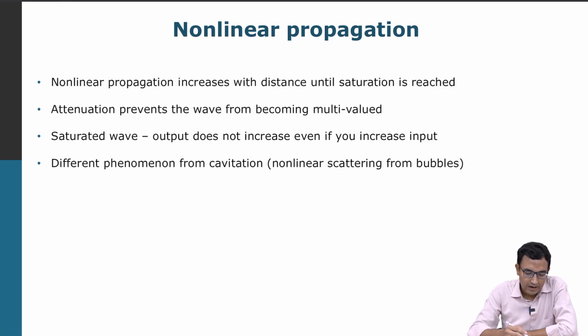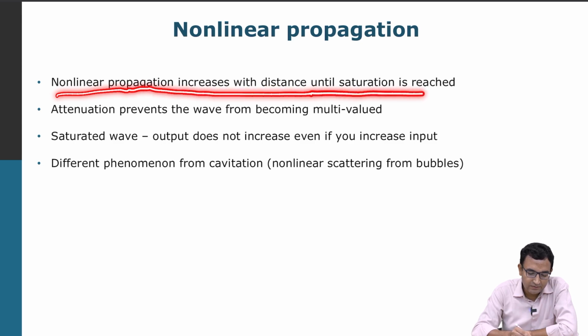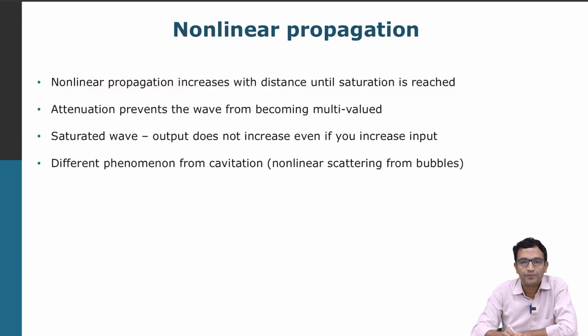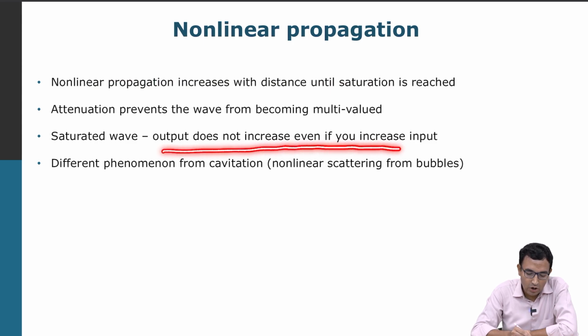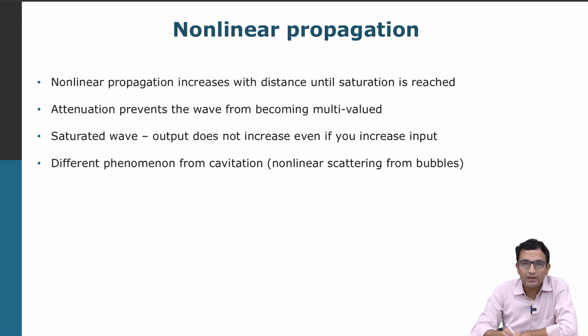So now let's talk about this nonlinear propagation. Nonlinear propagation, because the nonlinearity builds as the wave propagates further, right? So nonlinear propagation increases with distance till saturation is reached. But once you have the saturation, right, the output is not going to increase even if you increase the input. Because any increase in energy that you are giving, the higher frequencies that are generated because of the nonlinear wave, or rather the distorted wave, will be very quickly absorbed.